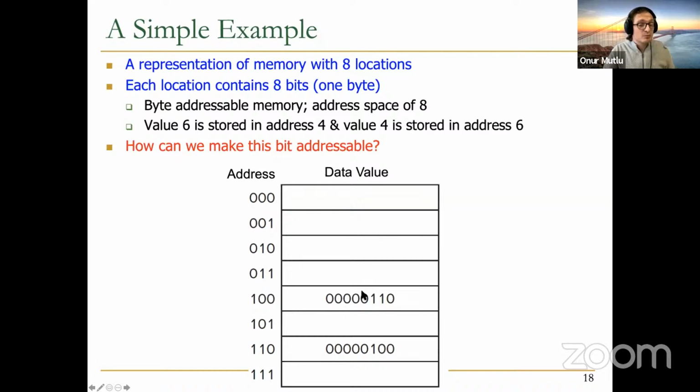And the programmer specifies which bit they want. So you can basically get these 8 bits out in the underlying hardware. And then the programmer provides 3 more bits saying which of these 8 bits they want, if you have a bit addressable ISA. Then, after you get these 8 bits out in hardware, you put those 8 bits into a mux, and the multiplexer basically selects the bit that the programmer wants.